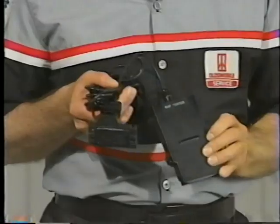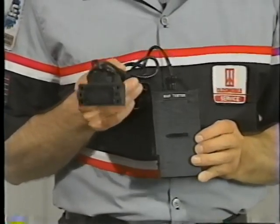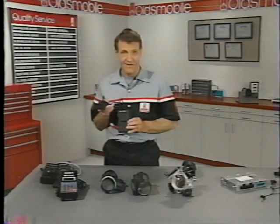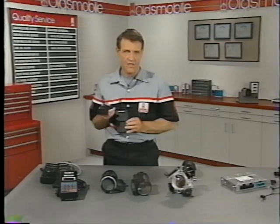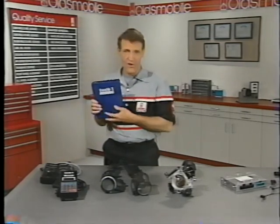this special Tech 1 cartridge. It's the MAF tester cartridge, and it comes with a cable and an attached MAP sensor. That's MAP with a P. The setup uses this MAP sensor as a reference during testing. The tester comes with a supplement for your Tech 1 operator's manual.